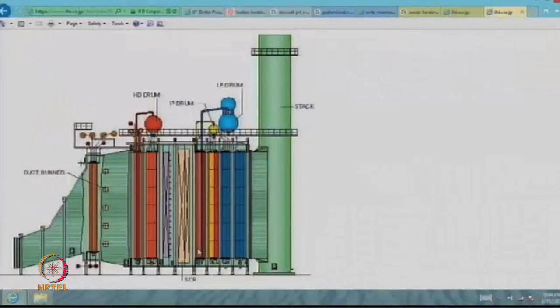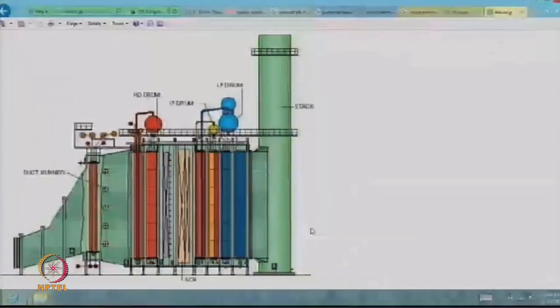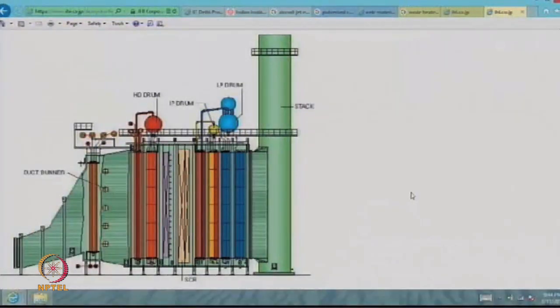Why can't we go to 5 degrees or 4 degrees or 3 degrees? So the thermodynamics tells you that's good. The practical thing tells you that to do that much heat transfer, you need a very large size. So you need more space. The amount of material required is very large, and that adds to the cost of the plant, and so we don't do it. And so what you see in practice is a sort of a compromise between what thermodynamics tells you you should do and what the practical world of engineering and costing tells you is possible and not possible. So every design is specific in that particular context.